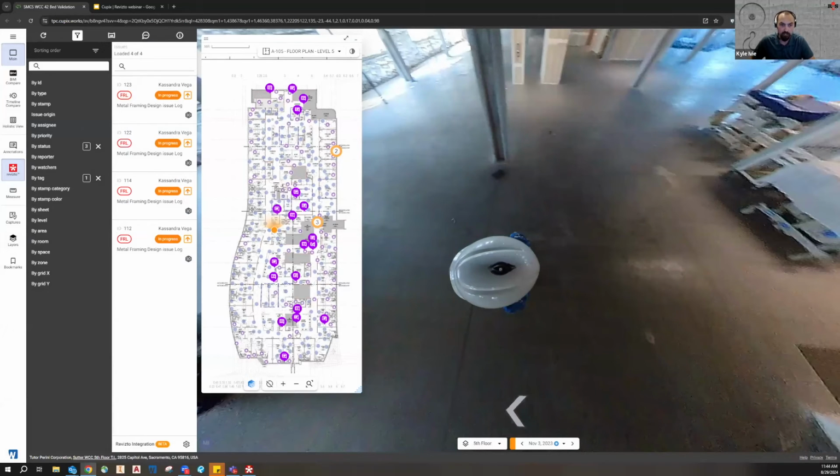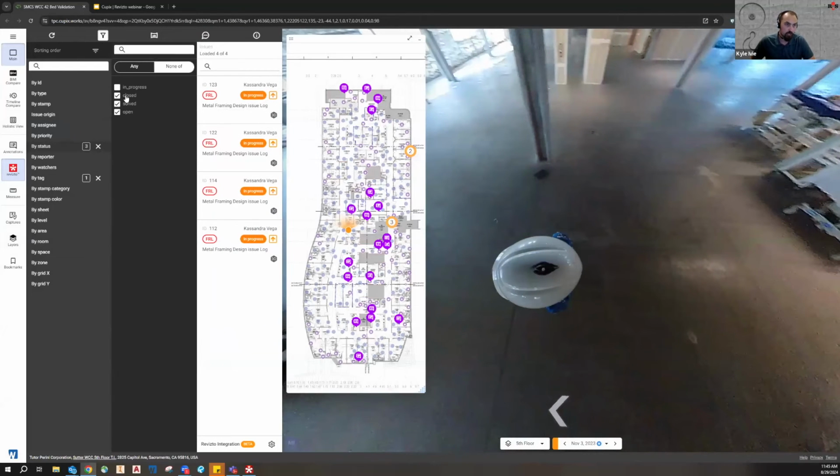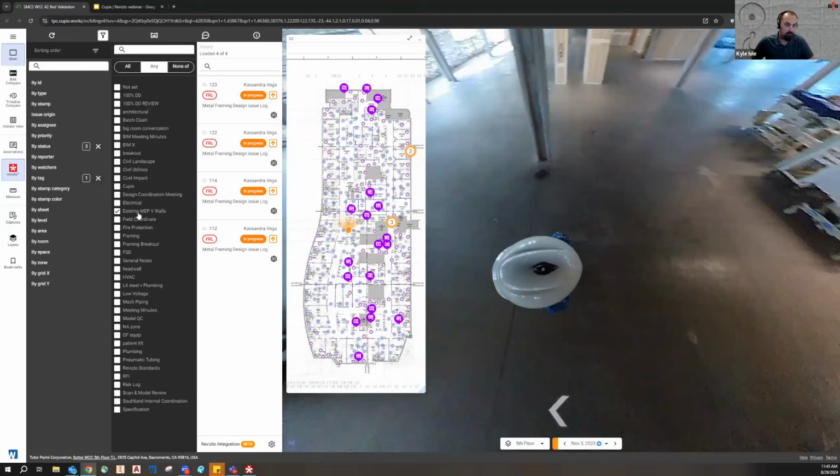You can see the floor plan here, and you can see these filters that I have selected are very similar to the filters that you would see in Revizto. So it's using the parameters that build our presets. At the top there, you can see I've got the funnel selected. That's our filter. Within there, I've applied 3 options for the status, which is not showing any closed, solved, or open. And then for tag, I've selected one of my pre-made tags from Revizto. With that, you can see that it's isolated 4 specific issues to my list here.